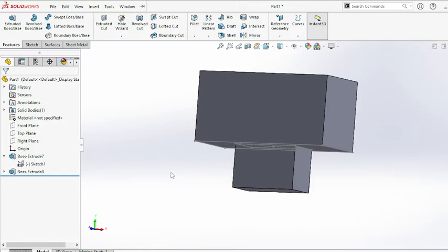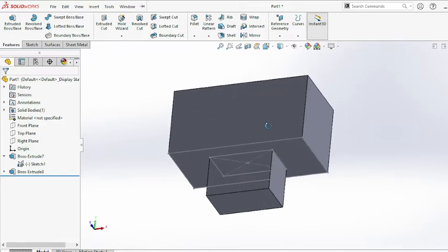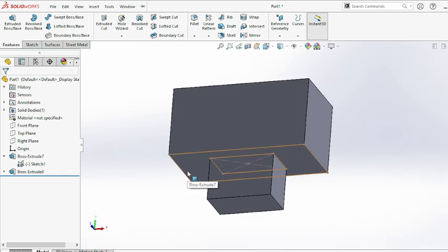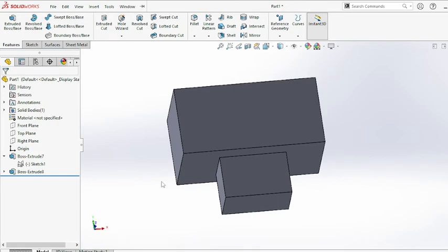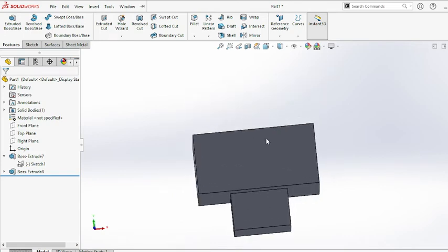Okay, so compulsorily you must show your sketch. At that time only the sketch is visible, right? So select the sketch, right click. Select the sketch, after that only your eye symbol is there. You can hide this one also. Okay, so once I draw two rectangles, you can select them separately also, no problem.